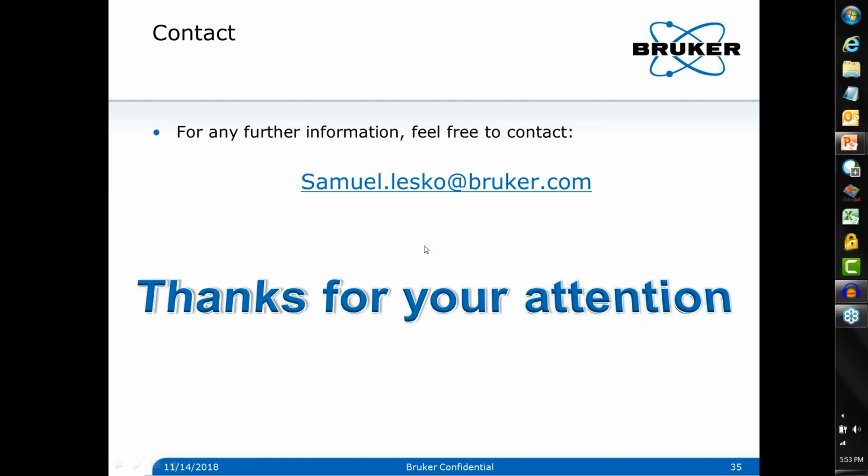In that instance, again, focus variation should be used for what it is good for, and likewise, white light interferometry should be used for what it is good for. White light interferometry has unique capabilities to measure a large field of view with even sub-nanometer vertical resolution, and that's a unique strength, in the same way that focus variation is able to measure rough samples.